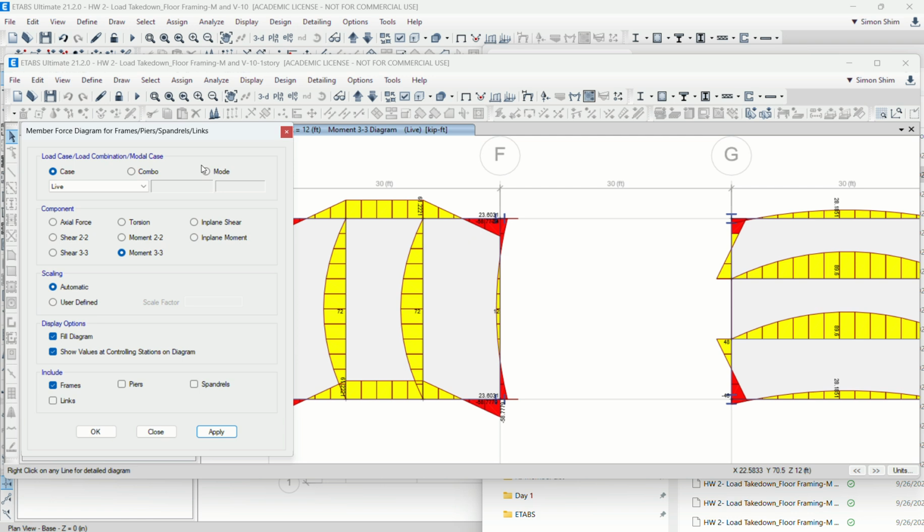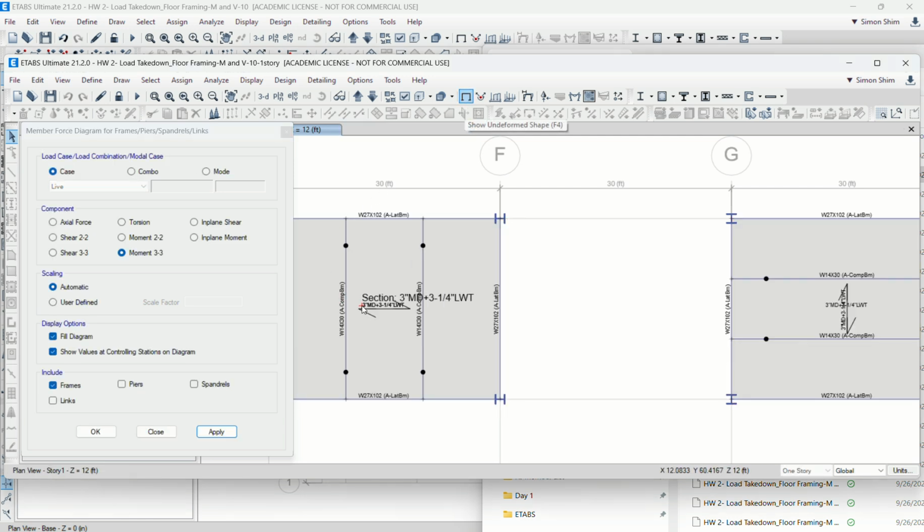For most buildings, we need to start from the slab and beam, and then girder, and then column and foundation, because this is how the load actually goes down. So this is simple math, but very important, right? Remember the WL squared over 8. This is on a uniform load basis, but in order to get to this level, you need to understand the geometry, right? The space, how the structural element is spanning. The orientation matters.